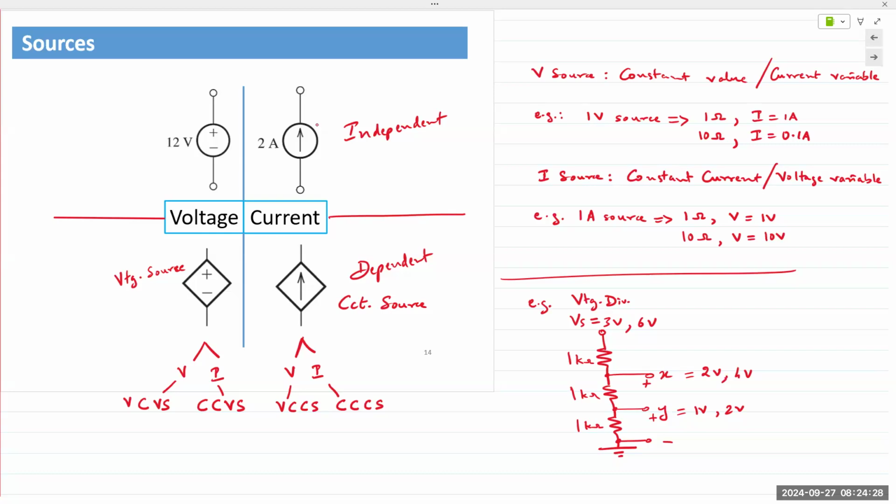Okay, so the question being asked is, does it relate anything to do with the current limit or the voltage limit we set on the power supplies? No, that's just the real life power supply. When we perform theoretical analysis here, everything is ideal. If it's a current source, we could connect like a 0.1 ohm to like a 10 amp source, and it would say it's like 1,000 volts or 100 volts or something that's coming out. Realistically speaking, we could perhaps design something like that to work, but that's not something we'll encounter. So the answer would be no.